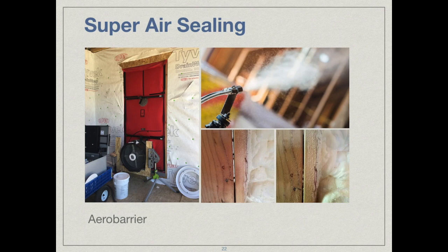Generally, you do need to continue to do the basic caulking. The AeroBarrier will work on gaps and cavities that are 5/8 of an inch or less. So the large openings still have to be treated somehow, but the smaller ones can be done in this way, and you can really dial in the amount of tightness that you want. So a good thing to consider going forward.